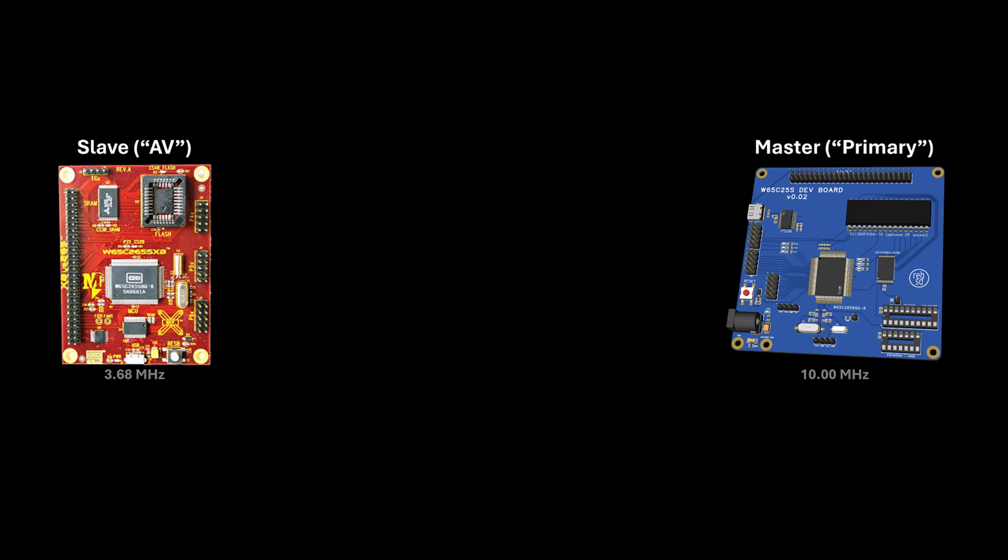Now on the right is what my board looks like. This is my custom 265 board. It's almost identical in functionality to the board on the left. Really the only big difference is I've put in a ZIF socket for the external flash instead of the PLCC socket. And I'm doing some extra decode for other peripherals that the 265 by itself can't do. And I'm running a faster clock: 10 megahertz for my Phi 2 versus the 3.68 on the WDC board.